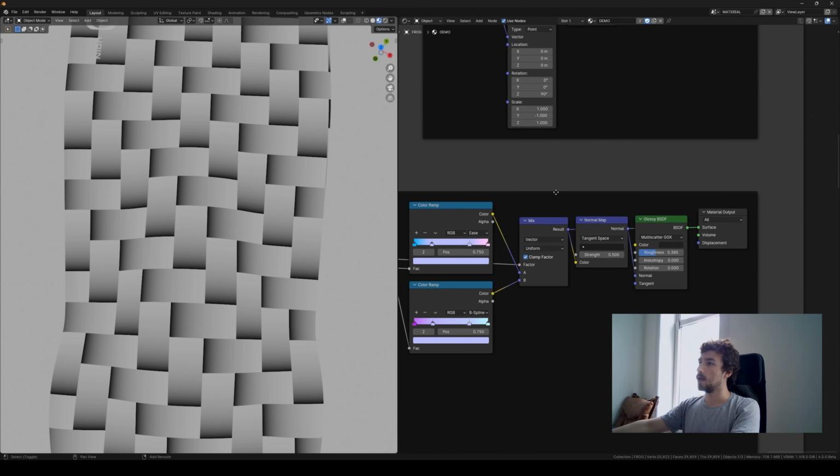So we said that you can decide if the reflection will be more on the x-axis or the y-axis, etc. So here what we can do is that we generate a normal map where on one direction we go with just sideways, and on the other one vertical, and we combine those two to create this, that we can just use it as a normal map then and create this effect of just the base weaving, basically.